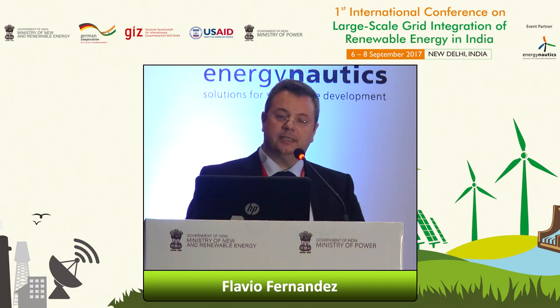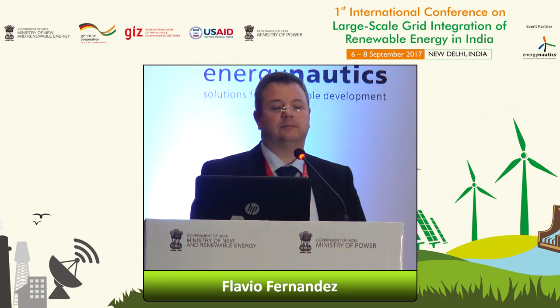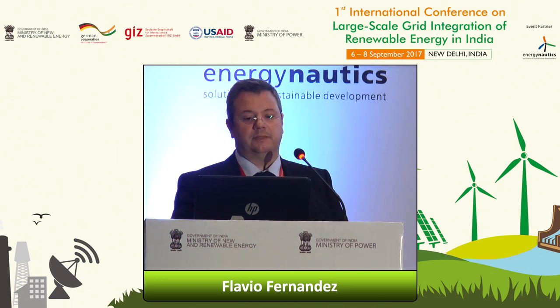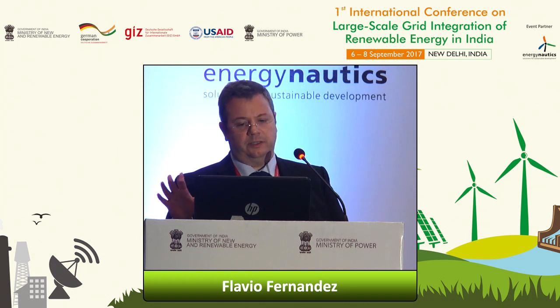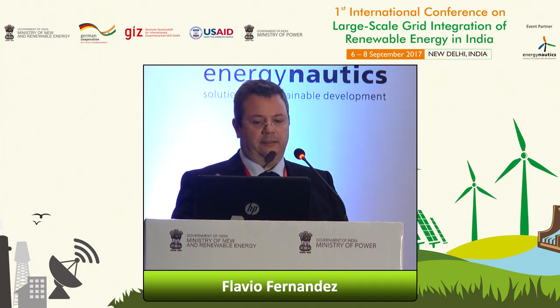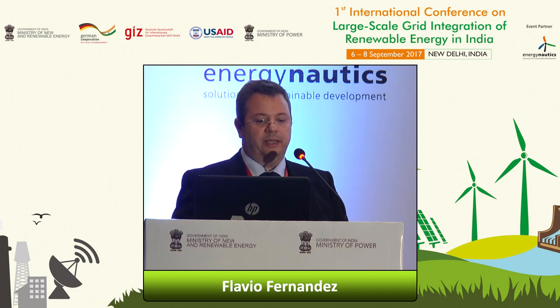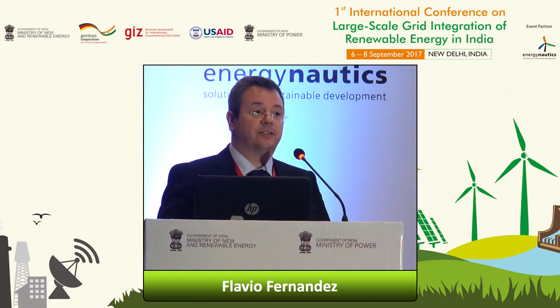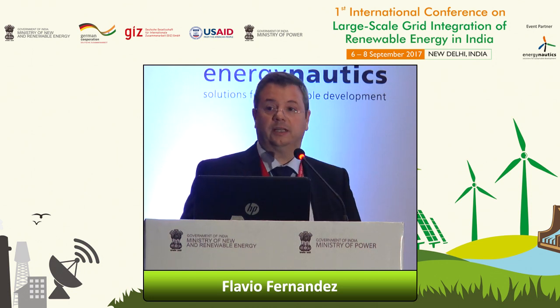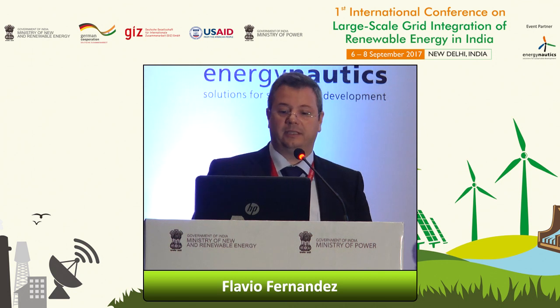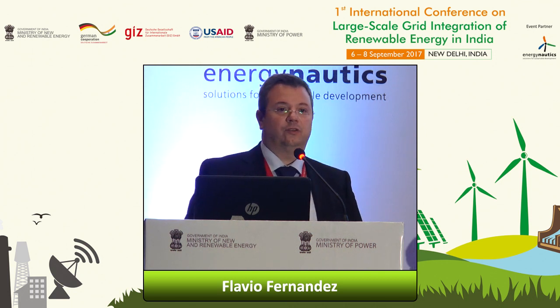Certainly further standardization is required in terms of dynamics for other systems like storage, battery storage systems. Dynamic modeling of distribution networks with embedded generation is certainly also an issue. Other FACTS components are probably still missing, at least in the ENTSO-E, in the European experience. Data exchange, the CIM for dynamics, is ongoing. I think this will also be the future. And then maybe a last point I bring here for discussion is the dynamic network reduction. At some point you need to aggregate, you need to reduce, and how to do the network reduction, a dynamic network reduction under consideration of the nonlinear behavior of the generation.